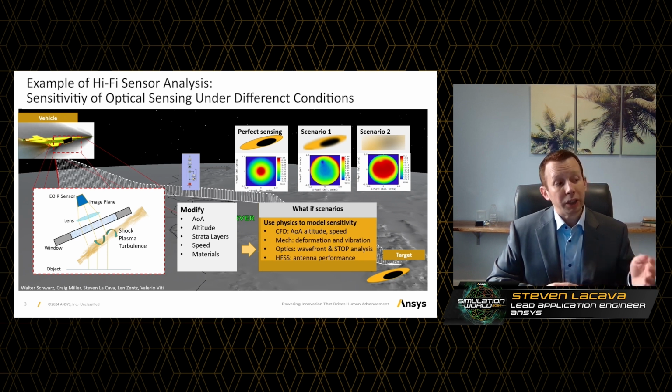In addition to that, as we increase to higher and higher speeds, the air in front of the window is going to become turbulent. You get going fast enough, you start to see shock waves. You get going even faster, and you begin to get separation of molecules. You go even faster, you get ionization and plasmatic effects. All of these are problems from an optical standpoint, and all of these are issues that we really need to deal with.